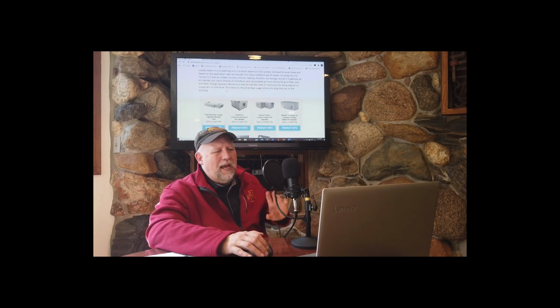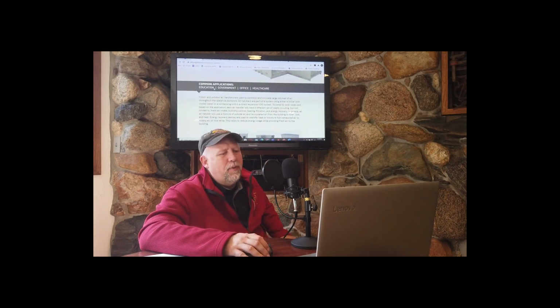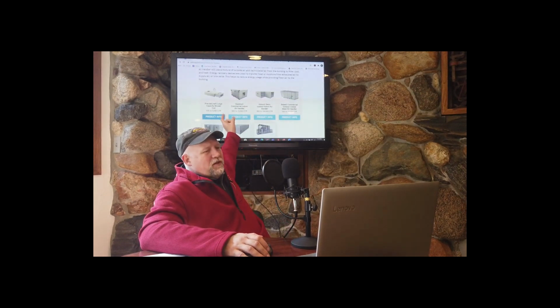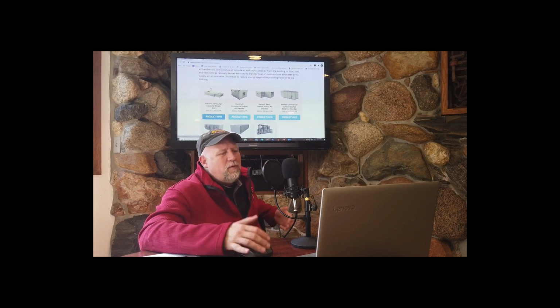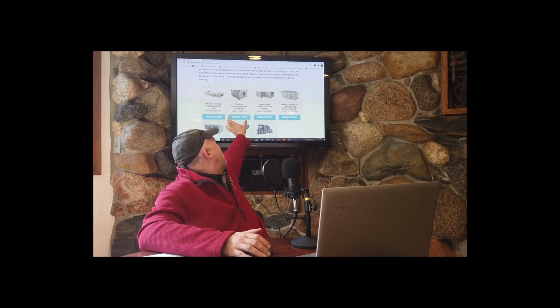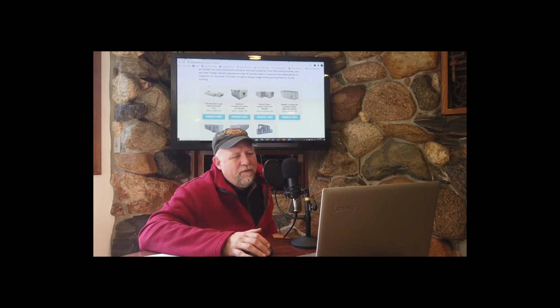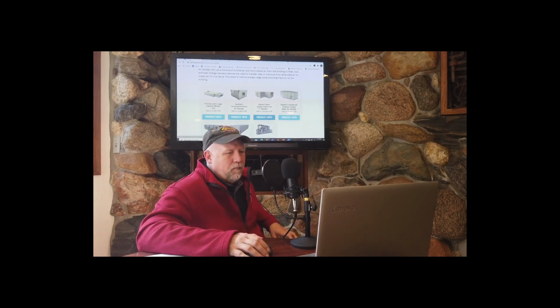Here, at a glance, looking at Daikin applied products, we've got the small ones, they're basically just a coil and a fan. That's why they're called blower coils. They only go up to about 5,000 CFM. We've got our commercial air handlers. Think of these as like factory, off the shelf. You don't get a whole lot of options, and they go up to about 15,000 CFM for indoor air applications.